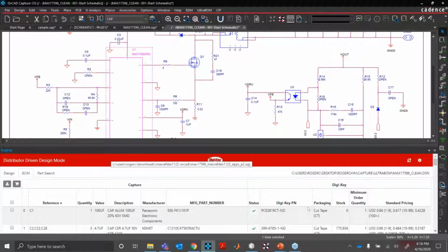How can I share data downloaded using UltraBOM? So if you want to create a bill of materials, you can create a bill of material report this way with UltraBOM, but we highly recommend having all your engineers have UltraBOM inside their OrCAD environments so that you do the mapping once and you can see that real live data by using a refresh whenever you open up your design. So that's the best way of sharing that design if you're using UltraBOM. Again, there are other component database systems that have direct links to Digi-Key as well, like CIP, that will handle that in a more centralized way.